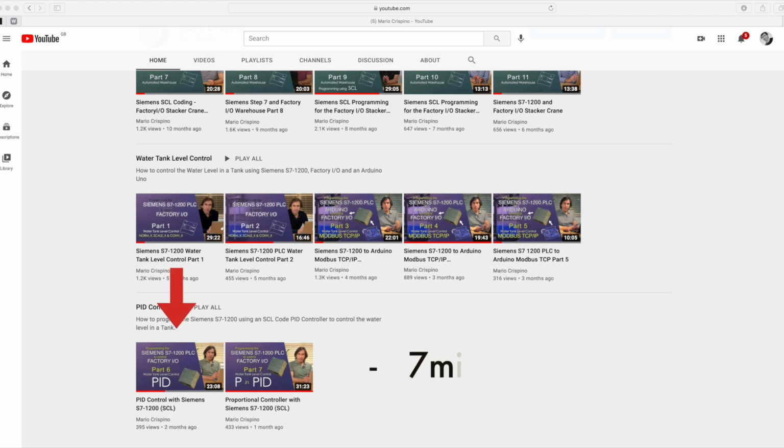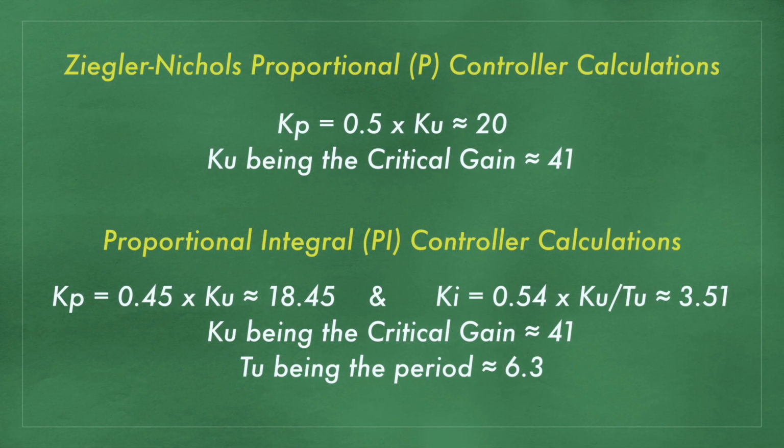You can see this in the first PID video again at 7 minutes 45 seconds. So Kp works out to be approximately 18 and Ki approximately 3.5 as a starting point. However, instead of using 3.5, I'm going to work my way up from 0.3.